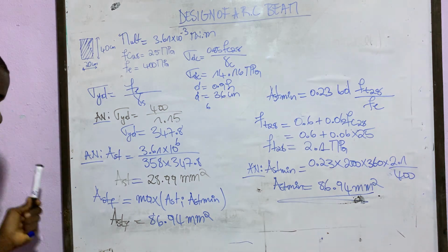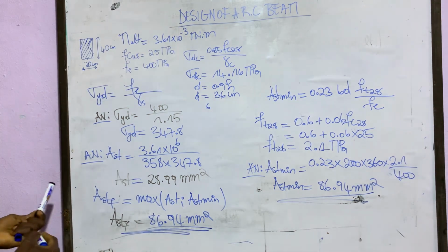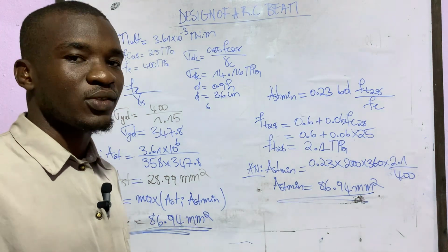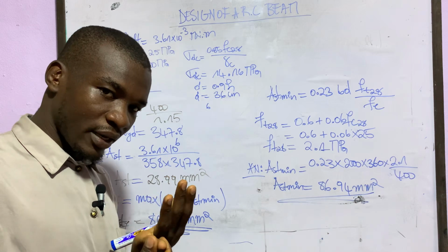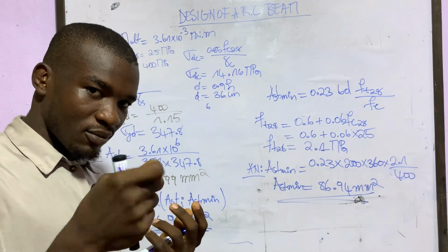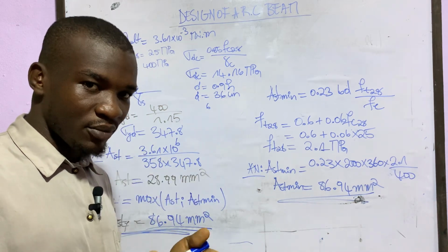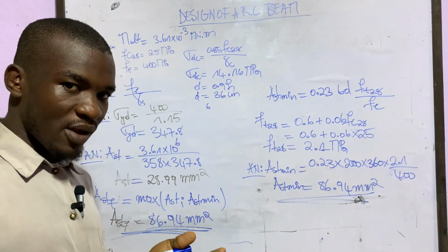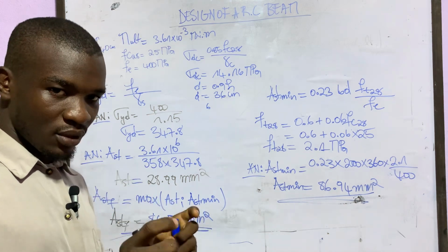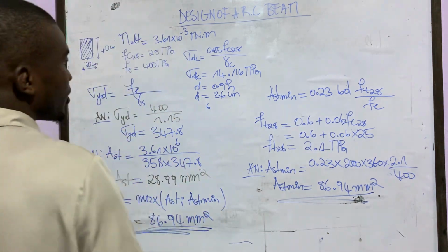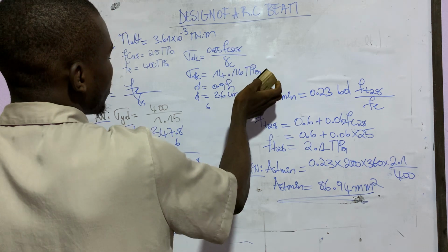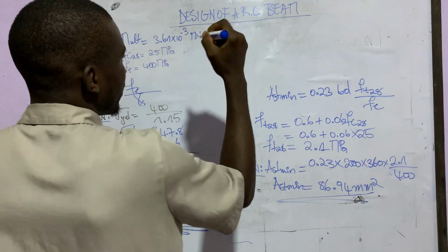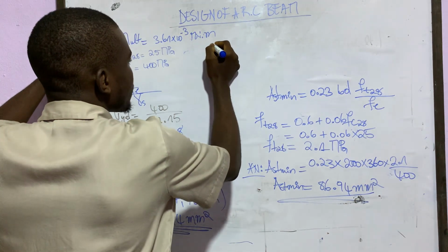When you reach here, you can say you are done with your design, because what is left is just to determine the diameter of your reinforcement, the diameter of your steel bar according to their geometrical area, and the number of reinforcement. Remember, you are in pivot A, so we are trying to reinforce only in the tension area. As a bonus, you just use this formula.